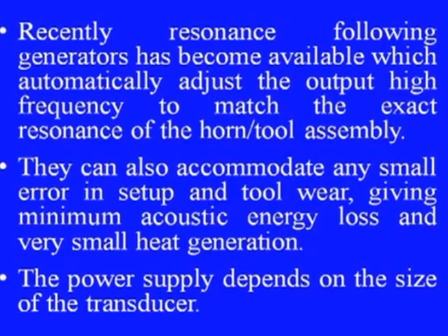Recently, resonance following generators have become available, which automatically adjust the output high frequency to match the exact resonance of the horn or the tool assembly. This is an advancement as far as this tool is concerned, in which this matching of the frequency is very, very important, and this is being automatically adjusted nowadays.